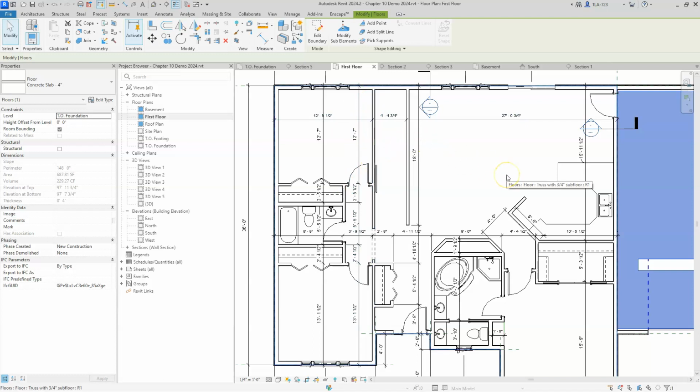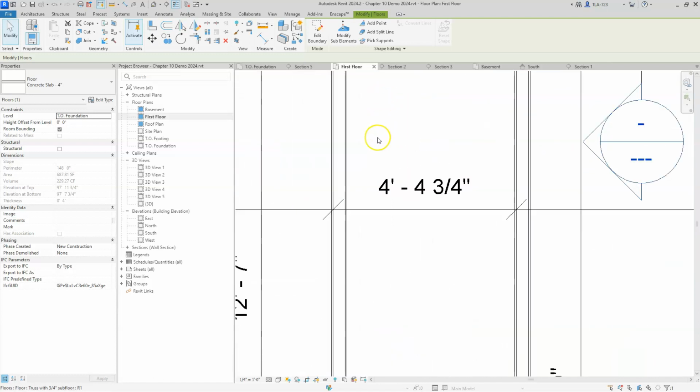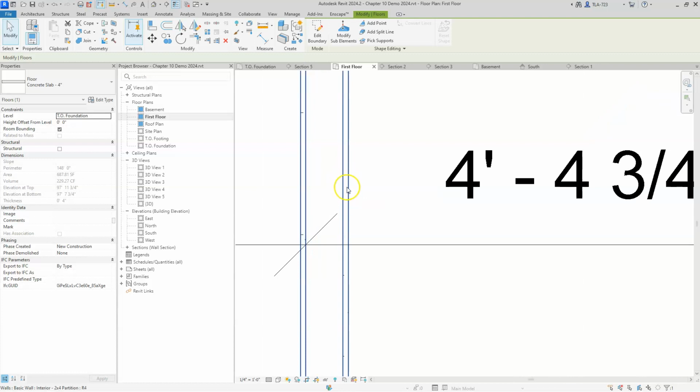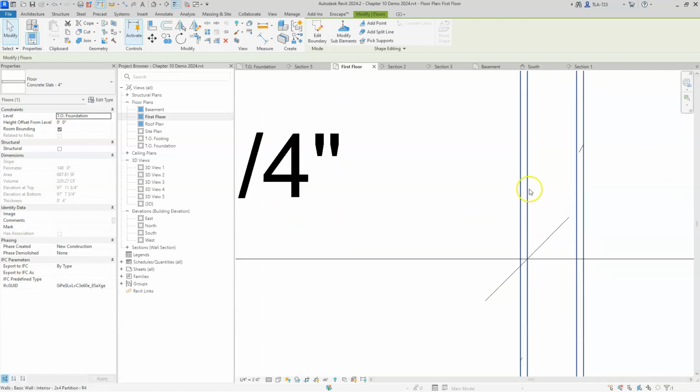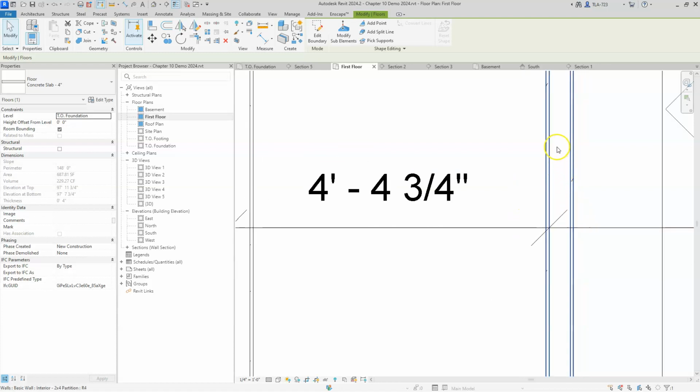So we obviously are going to have to create a hole in that floor, right? We call that the stair opening. You probably remember that term. But the question is, where do we stop that floor? If they're actually going to frame this floor out, where would they create the boundary of that stair opening? And the answer, as you may have already guessed, is going to be aligned with the outside face of the stud on each of the boundary walls. Okay, so those walls will be built, they'll be framed right at the edge of that opening.